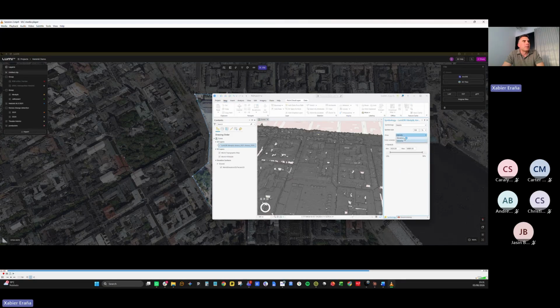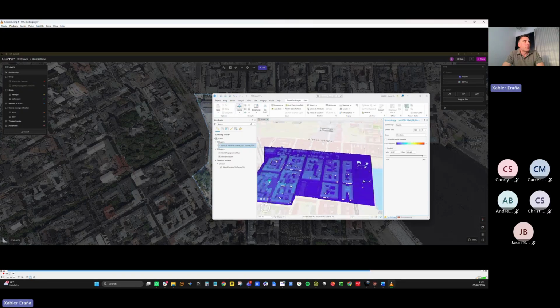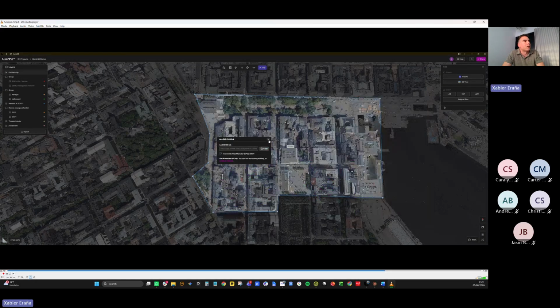There we can see the different visualization possibilities within ArcGIS. Remember that I3S is a visualization protocol. If you want to process further this data in ArcGIS, you will need to use a tool called Extract LAS. Simply input the point cloud we are using, the target folder, and run the tool. It should take not more than half a minute, and you will have your data ready.